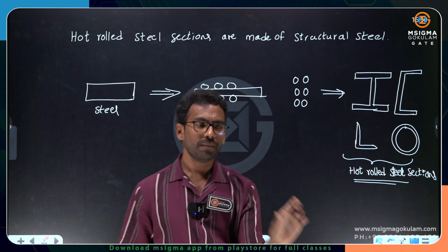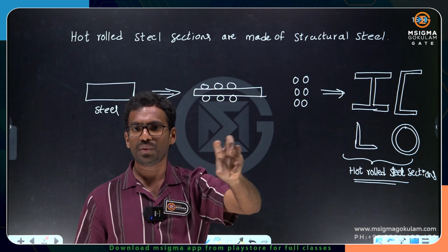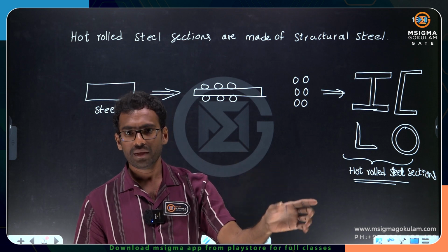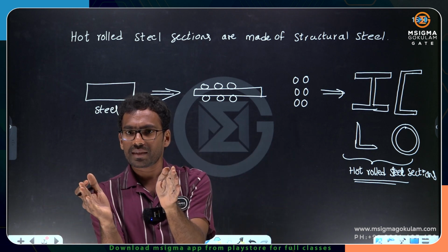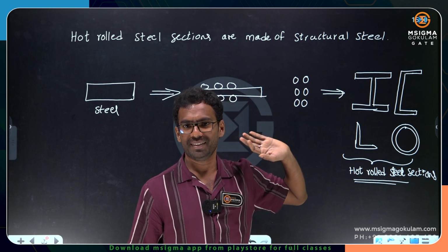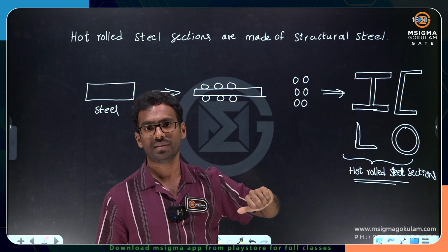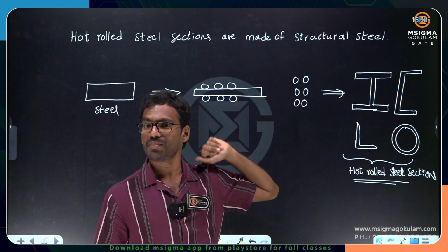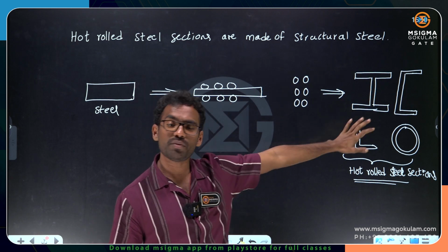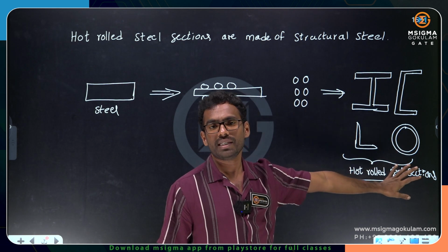So what is a steel structure? Listen, not only these 4, we have 10 types of hot rolled steel sections. Basically, we are getting them from Indian rolling mills. So any steel structure you want to construct, you take a few of them or all of them according to the nature of construction, type of construction. We can use all of them also sometimes. So such kind of structures which make use of these hot rolled steel sections are basically called steel structures.